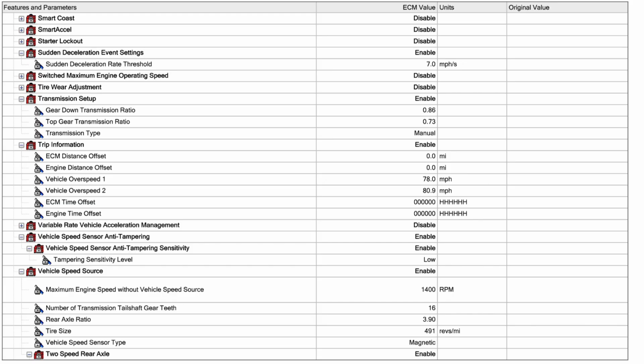So if the guy's going 70, if he slams the brakes on and he's slowing down 7 miles an hour or faster per second, it's going to log a fault code. He doesn't know it, but when they pull the faults, they'll see that fault code. And if he slams the brakes on 30 times in a trip, you'll see 30 of those fault codes. It doesn't derate or do anything else. It's just a tattletale.